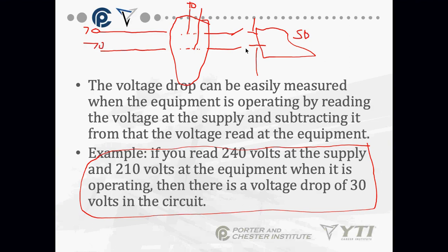Who here has a high efficiency gas furnace in your basement? I know somebody here does, with the PVC vent piping that goes outside. Those high efficiency pieces of equipment, believe it or not, have voltage monitors on the circuit board. If the voltage drops, the equipment's going to trip out.